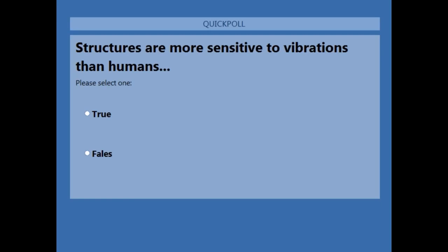Steve, next question. Who determines the number and location of monitoring points? The number and location of monitoring points a lot of times is part of the project specifications. They may specify 3 monitoring points. They may have general locations, and there may be a note in there that says these are general locations subject to change based on field conditions. A lot of times these seismographs, these monitoring points, do move around based on the type of work that's being performed and the phase of work.